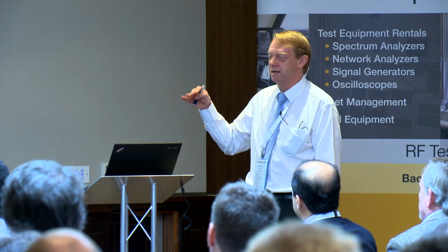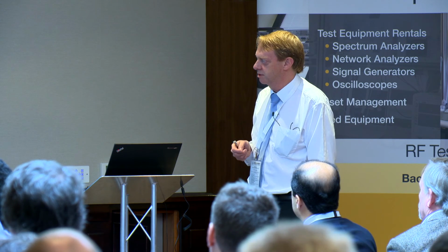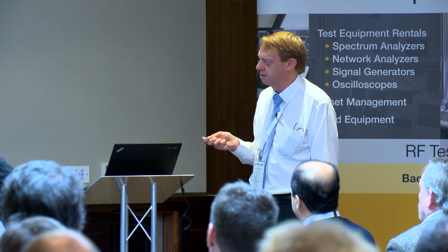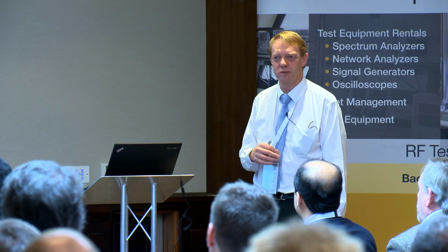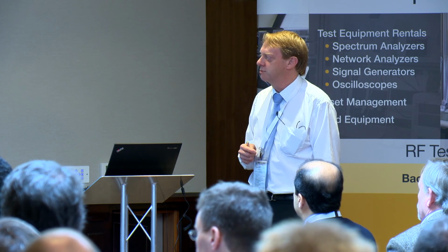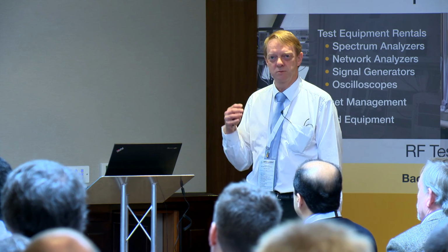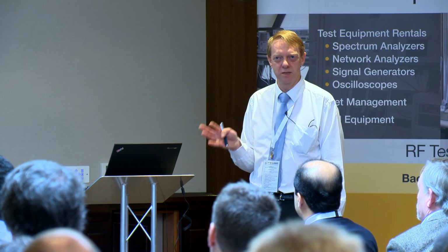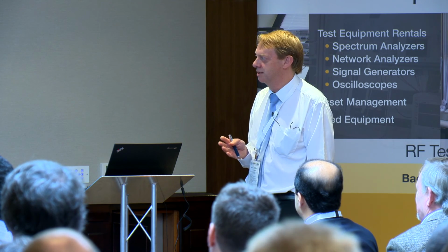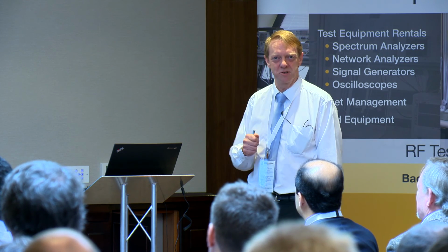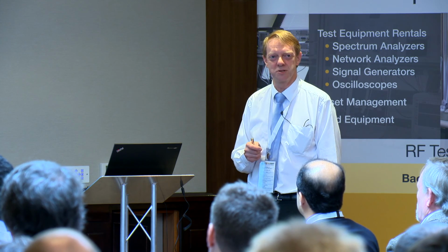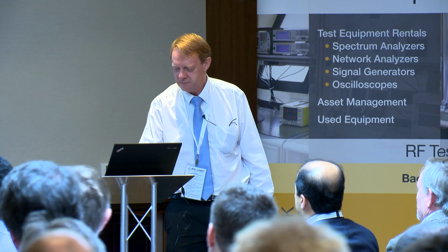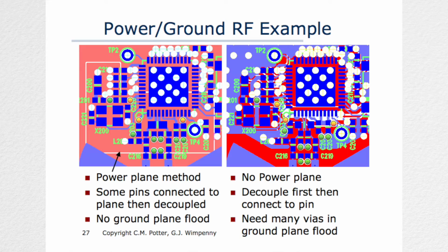I think ideally we would have had more dividing lines between the receiver and the transmit. And it's unfortunate that there wasn't enough room to get another dividing wall in that gap there. Then we wouldn't have had this problem even in the first place. But that's the way history works out. So unexpected magnetic coupling between inductors is something which has haunted me at least half a dozen times in my career. So I'm now looking out for that as the first thing whenever I see multiple inductors on the circuit board. Are they orthogonal to each other or not? That's a good thing to think about when you're doing a circuit board review.